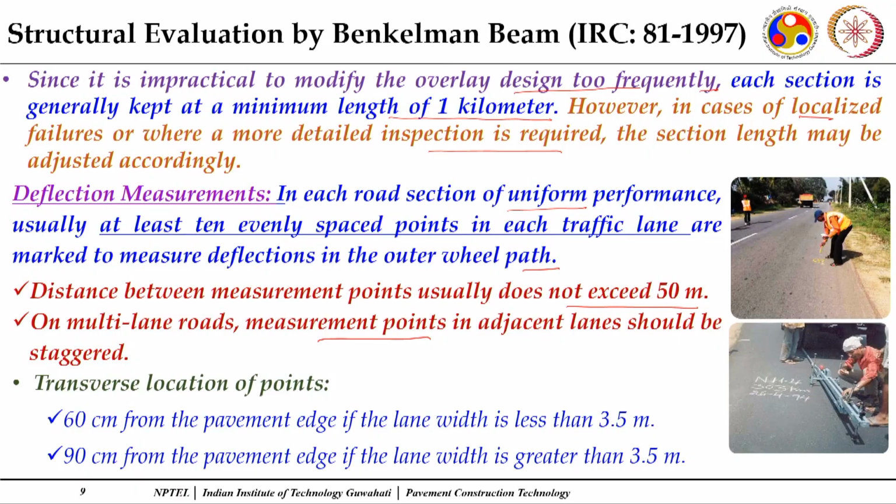So there may be a requirement to conduct this study on all the lanes. When we are doing it on the adjacent lanes also, we will prefer to do it in a staggered manner. So here you can see they are marking the points by chalk, by a moving wheel, along the pavement edge where these measurements are to be taken up.